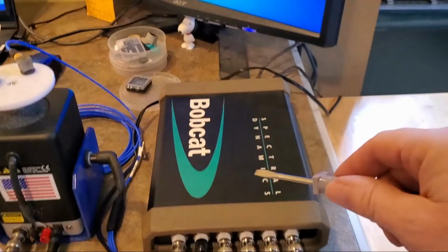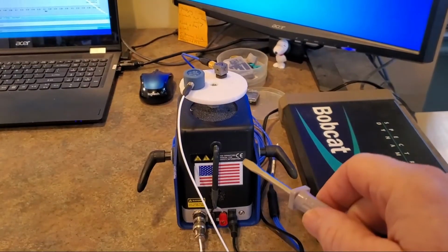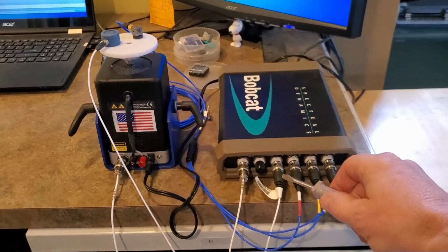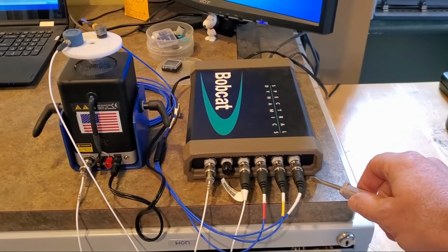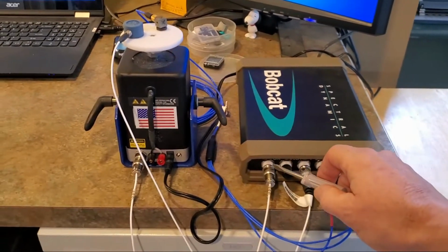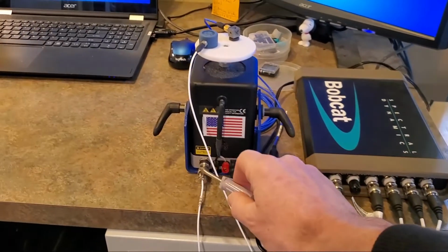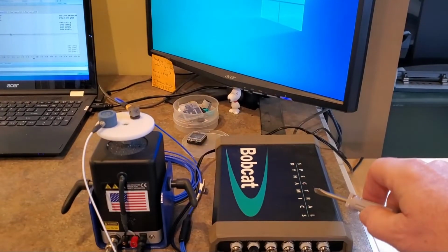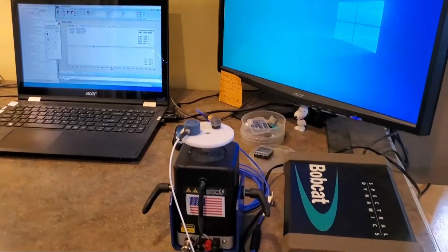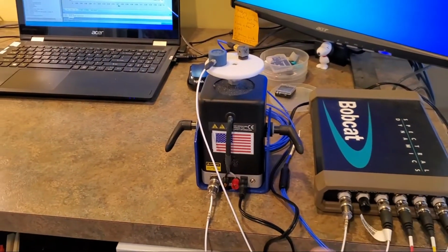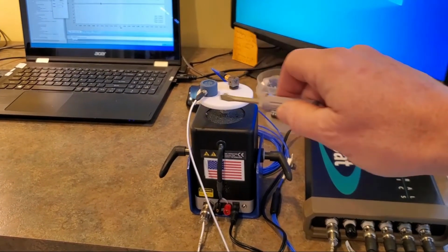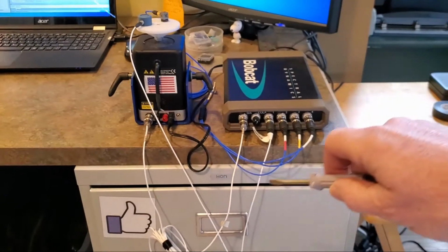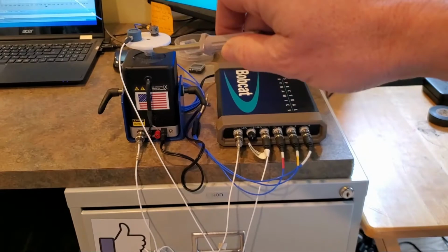Okay, cabled up to the controller, Spectral Dynamics Bobcat, PCB shaker. So these cables, the white cable goes into channel 1, the blue cables, X, Y, and Z, are into channels 2, 3, and 4. This is the output from the controller. This goes out and puts into the shaker system and drives the shaker, and then we measure it back into the controller. Over there is the PC hooked up to the controller with the software running. So this is closed loop control, where the drive turns on the shaker, makes motion. It's measured here with the accelerometers back in to the control system, and that goes in a loop, which is closed loop control.